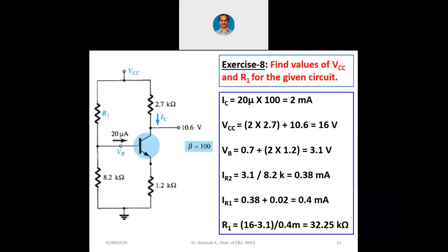One more thing with respect to the common emitter configuration is that when the input current is rising or the input voltage is rising, output current will be falling or the output voltage will be falling. This I had discussed earlier, which means when the input voltage is rising at the base, the output voltage at the collector will be falling because the transistor will be switching on towards saturation region.